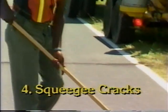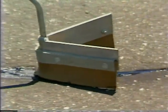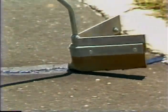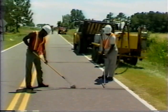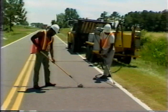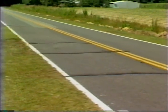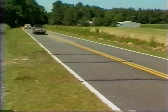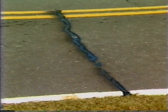Squeegeeing of the cracks is the fourth step in this procedure. Use a handheld squeegee to smooth out any excess sealant after application by the sealant wand. The squeegee follows immediately behind the application wand because the rubberized asphalt cools quickly. Once the sealant has cooled, the roadway is open to traffic. No blotting is required with rubberized asphalt. Using these operating procedures will result in effective crack sealing and will protect the pavement and retard future deterioration.